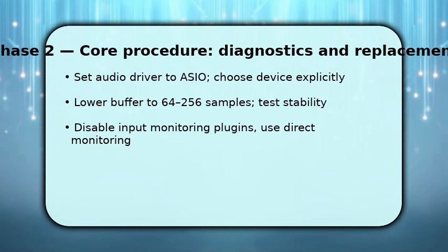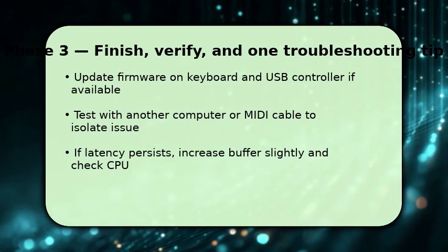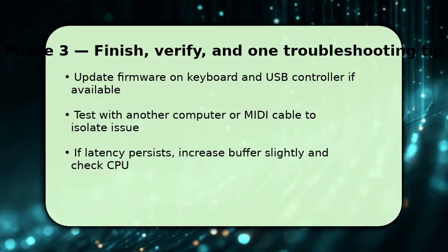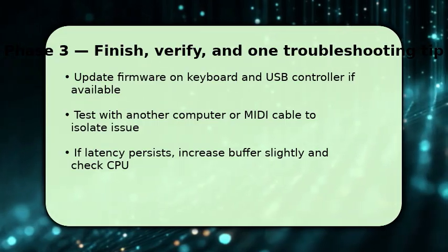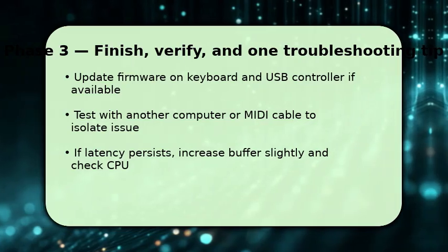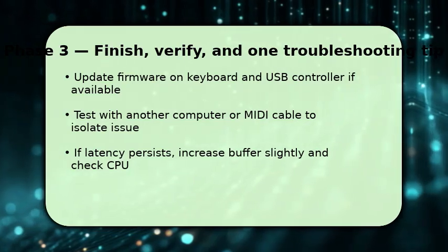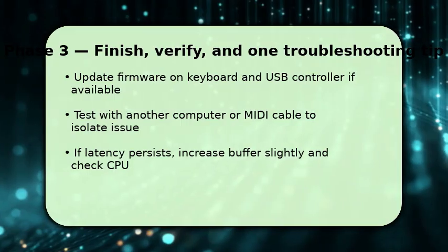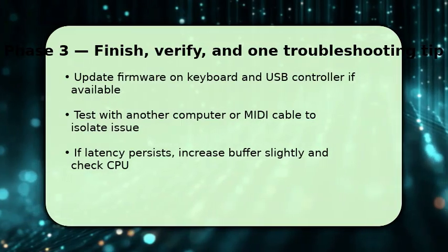Finish by updating firmware on both the keyboard and your motherboard or USB controller, because fixes often reduce USB polling delays. Then verify with a different computer or use a 5-pin MIDI cable through an interface to isolate whether the keyboard or PC is causing latency.